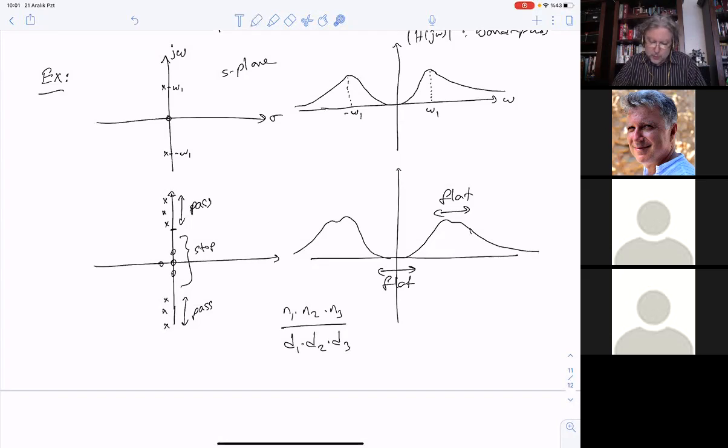If you move your frequency along plus infinity or minus infinity, these all will go to infinity, each one of them, equally. Therefore, at omega equal to infinity, it will make a non-zero, constant value. So h of j omega as omega goes to infinity will attain a finite value.